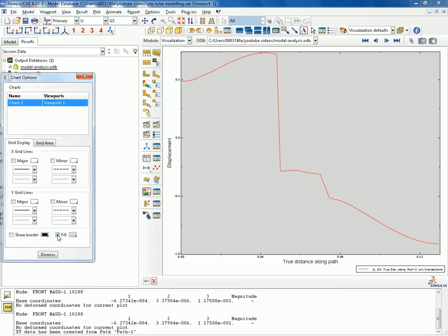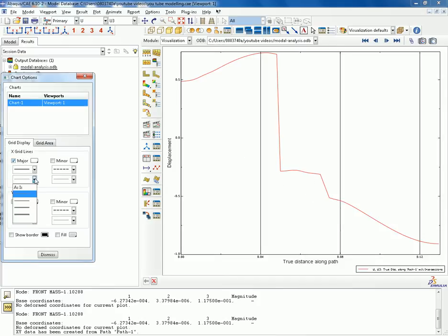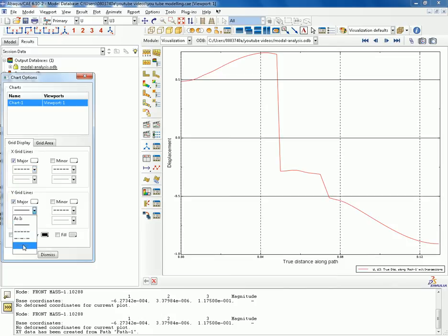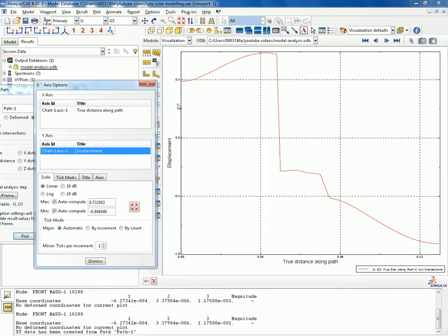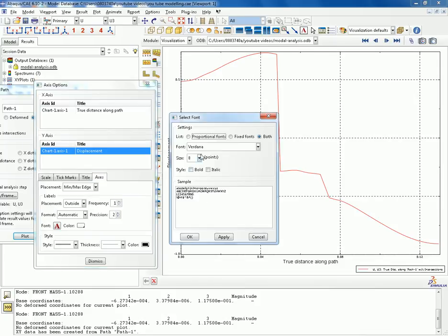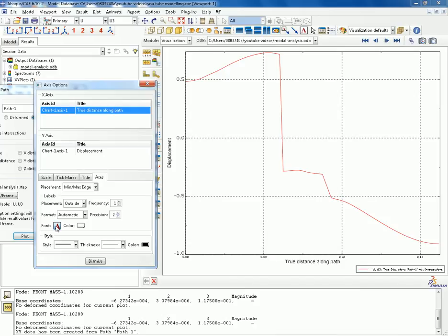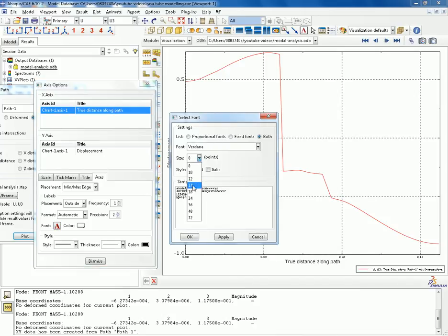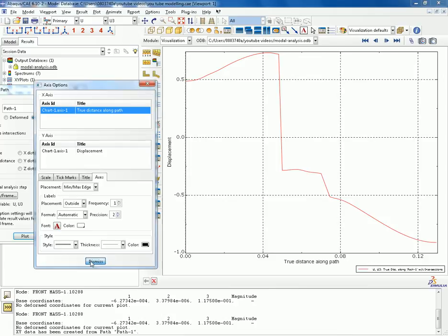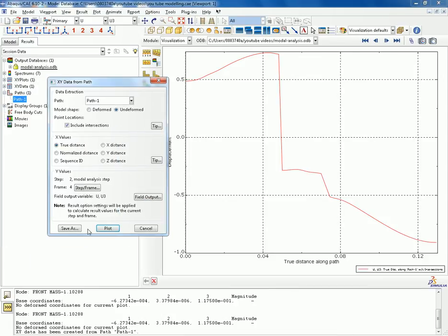So the ratio between the output value and the back value can give you an idea about the performance of your transducer. We're aiming in the transducer to increase the value at the output surface, or what they call the working surface, and reduce the amplitude on the back side, because it's not going to be used, so the energy delivered on this side is just lost energy. And to do that, you could either change the shape or the material of the back mass.